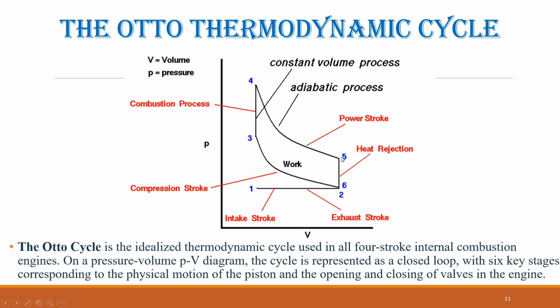Stage 4 to Stage 5, power stroke, expansion. The high-pressure gas expands, pushing the piston downward. The volume increases, and the gas does work on the piston while the pressure gradually decreases. This stage completes the main part of the power stroke.